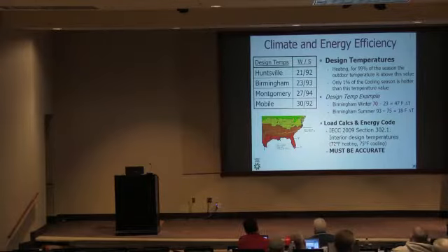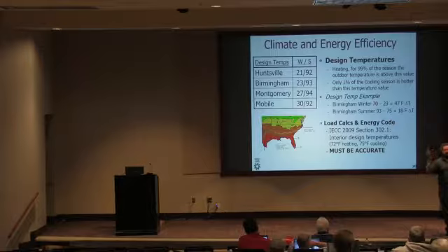The other thing is look at your surface areas, because Q equals UA delta T: area matters, insulation level matters. So if I'm trying to manipulate my load calculation, I may also increase or decrease, probably increase, my shell area to try and get a bigger system on the house. So look at the insulated surface areas and see if they're accurate to what's actually on the plan or how the house is actually designed.